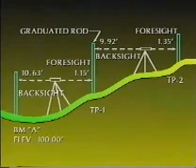The methods used in differential leveling are illustrated in your workbook and can be seen on the screen now. The level is set up some distance from a benchmark, and the direction the level run is to proceed. A benchmark is a permanent point with a known elevation, such as BMA. The rod is placed on the benchmark, and a backside reading is taken with the level. This reading is added to the elevation of the benchmark, which gives the elevation of the level. In this case, 100 feet plus 10.63 feet equals the height of the instrument, or 110.63 feet.